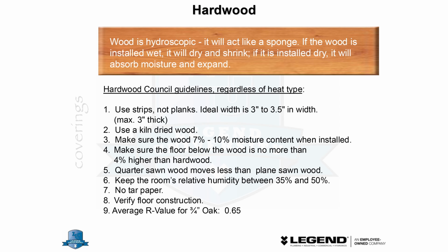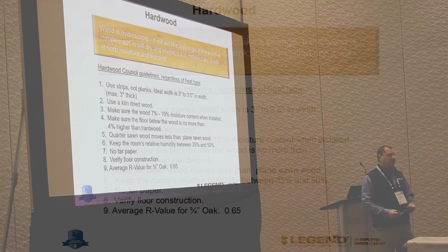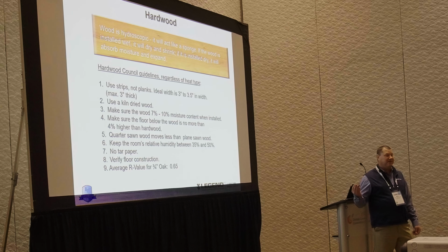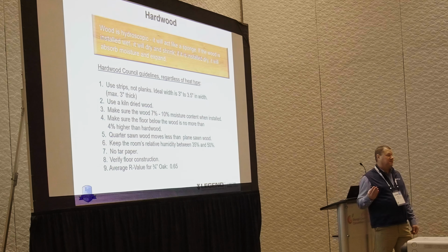Well, the radiant systems we're using nowadays have such low water temperatures. Using hardwood's not a big deal. But there are manufacturers' maximums for surface temperature. Anytime you're using a hardwood floor, you should consult that manufacturer and find out what their maximum surface temperature is.